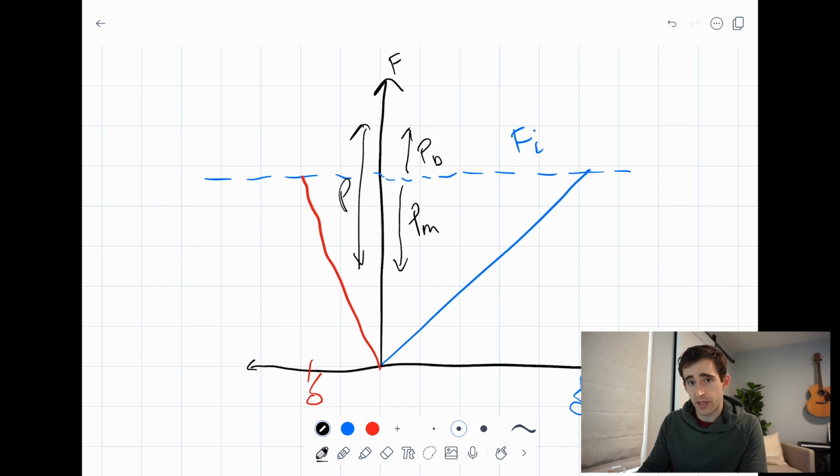So part of the applied load is going to go to the bolt, and part is going to go to the clamped material. What that's going to do is unload the clamped material, so we're going to decompress the clamped material, and we're going to only load the screw material a small amount more. And so if we have a high enough preload, Fi, most of the load is going to be carried by the clamped material.